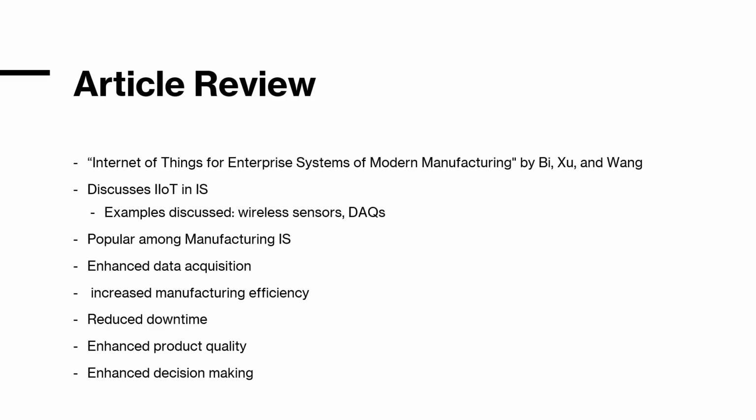With the Internet of Things, which is the connectability over Wi-Fi of different devices, you have enhanced data acquisition because you don't have to worry about running wires specifically from a sensor to a module to read. It can do it over a Wi-Fi signal, so you can get into smaller, tighter areas. You can have a better sense of what's happening in your process because you can put more sensors in more places.